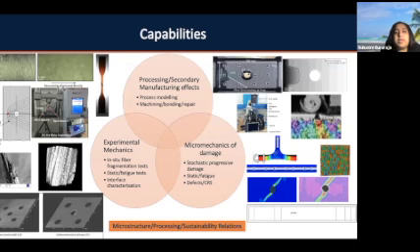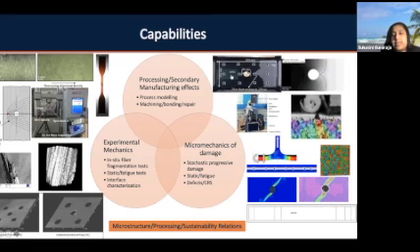In addition to that, that was as far as CMC materials go. We have also done quite a bit of study on polymer matrix composites. For example, one of my PhD students recently looked at a liquid composite molding process. He has developed a finite difference based two-phase flow simulation model using a level set approach, wherein he looks at the pressure difference, which is what's driving the resin to flow in this configuration.